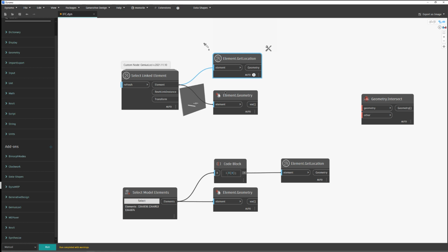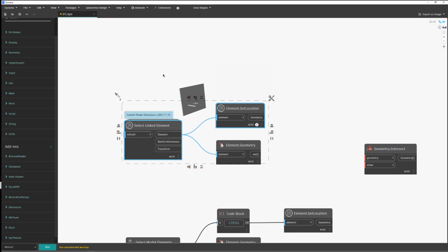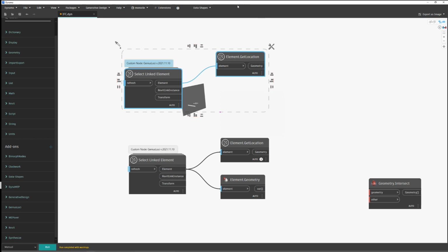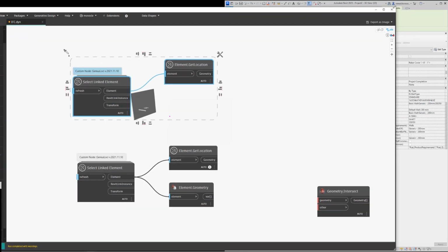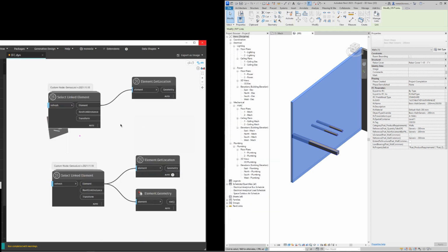If that is a Revit element and you want to get the location of the Revit wall element through the link, you will receive information regarding the location of the wall, and you will have a line. You can then take that line and use it to find the direction of the wall in order to find the rotation angle of your elements.